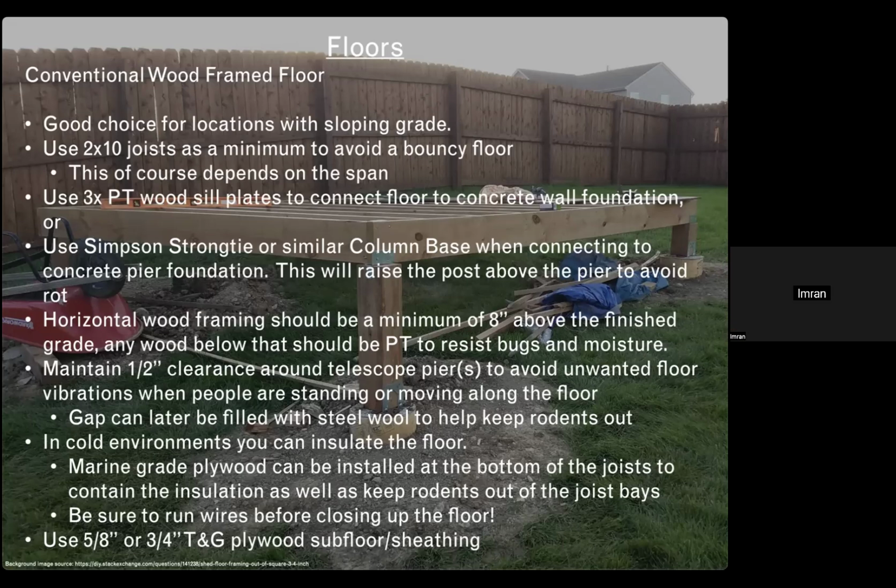Because I was just thinking, if I'm making a foundation and putting a steel pier on top of it, I don't need this thing, right? Yeah, you don't need that. If you're putting a steel pier on top of a concrete pier, you'll have your bolts coming out of the concrete and you would run them a little bit longer so that you can level the steel pier. Okay, got it.